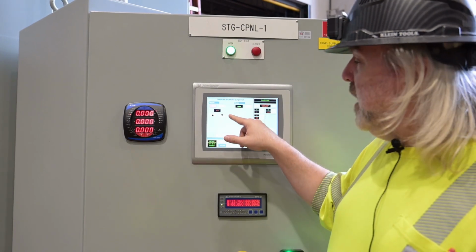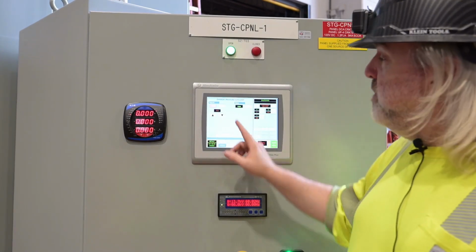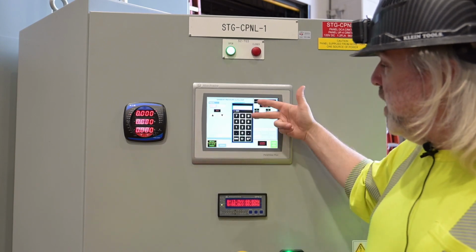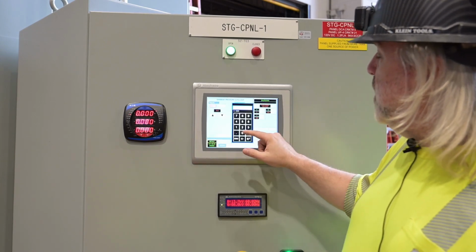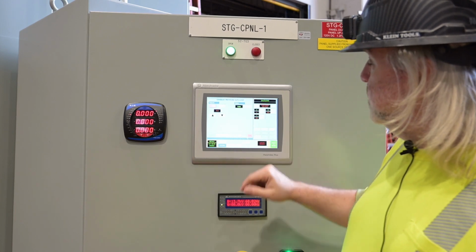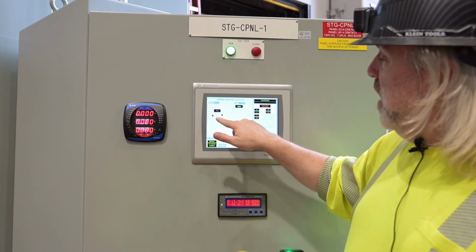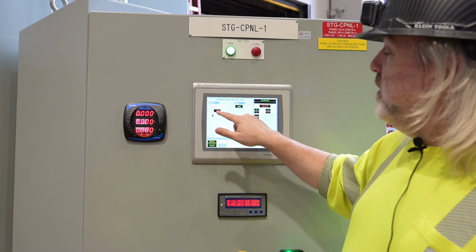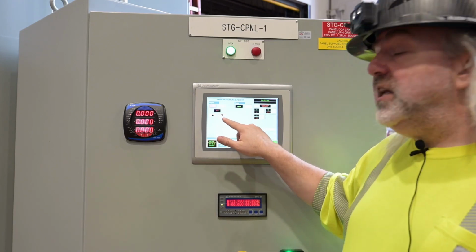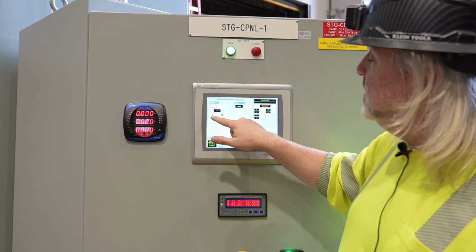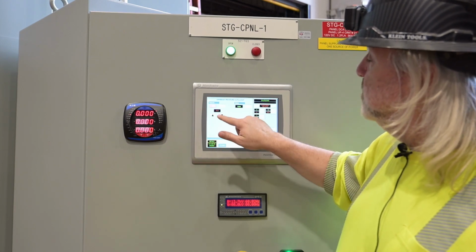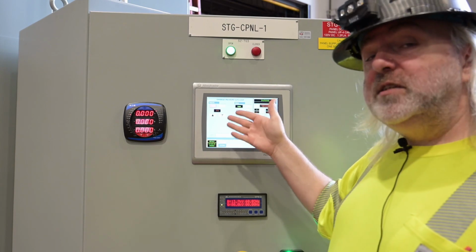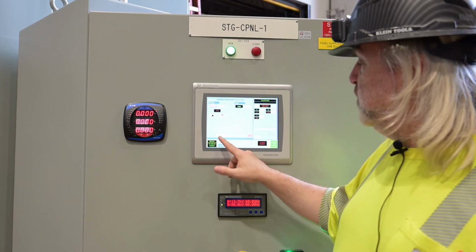Now, for set point adjustment, we have two methods. One method is to use the pink box. To do that, we press the pink box, bring up the numeric entry, put a new number in, hit confirm, and then ramp to that new number. You also have the ability to adjust it using your push buttons. In this case, I can raise it or I can lower it. That is the control. This is identical for all three loops.